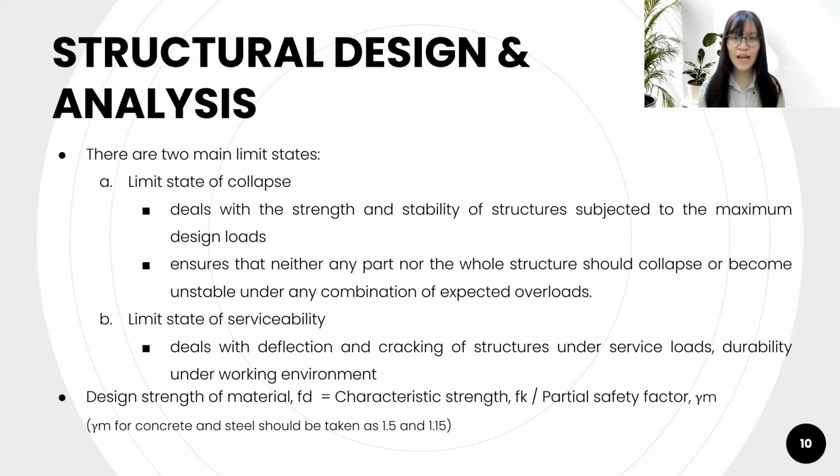It ensures that neither any part nor the whole structure should collapse or become unstable under any combination of expected overloads. Second, limit state of serviceability. It deals with deflection and cracking of structures under service loads, and durability under working environment.